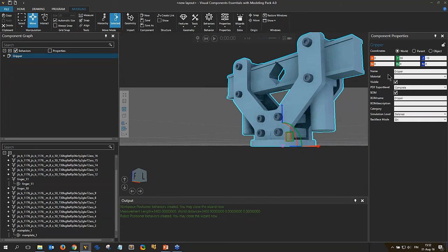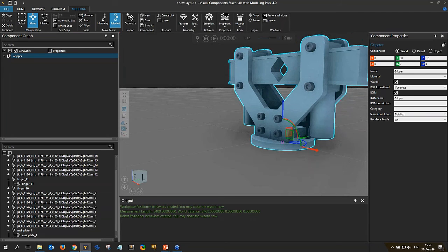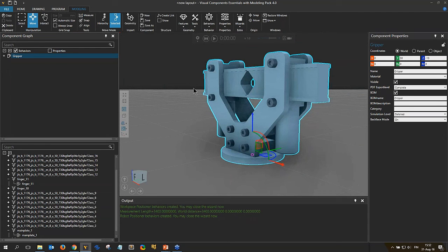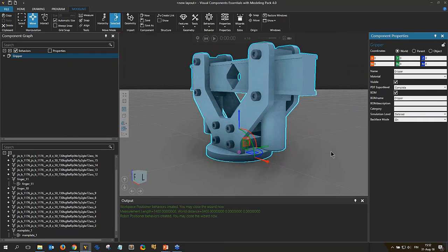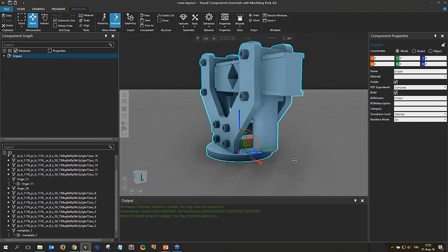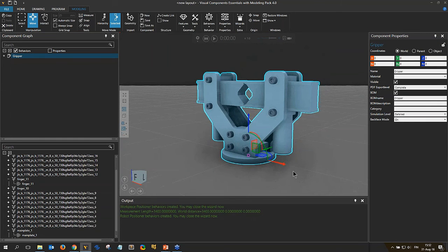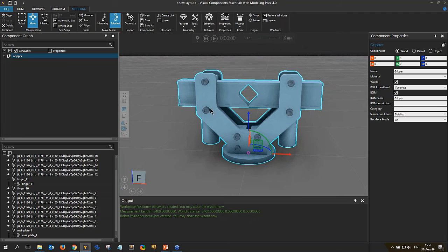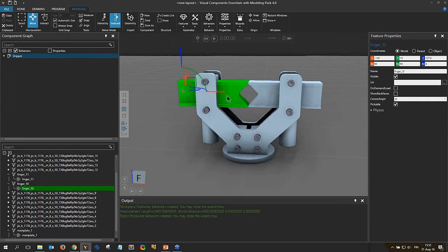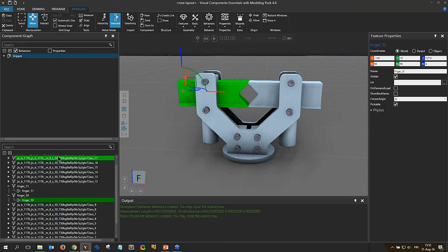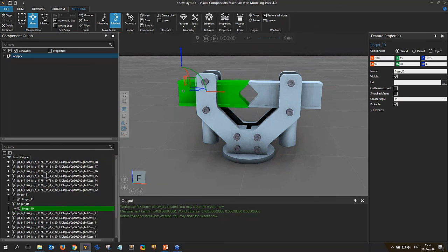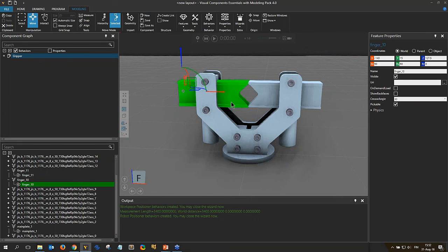You can also see that the component location has changed a little bit because everything on the screen stayed in the same place, but the origin is in a new place. So I will zero this out again, so we will get our component in dead center. Now we would like to make these little fingers, or whatever we call these, move. So in this case we get this full feature tree imported, so I don't need to explode or split or anything.